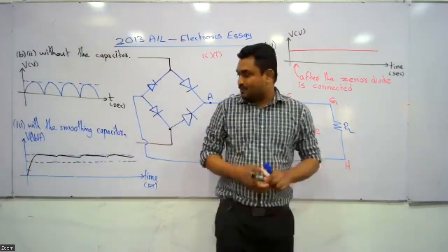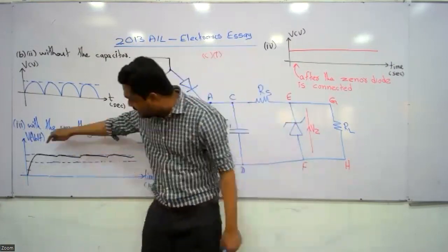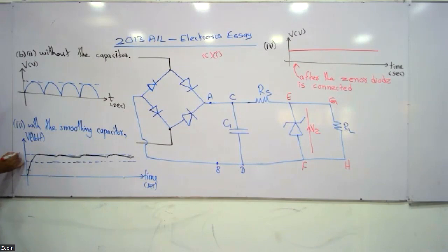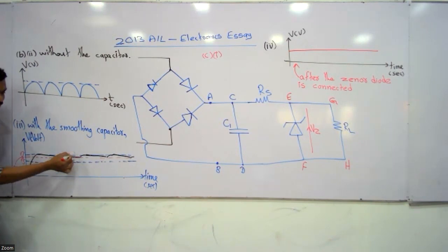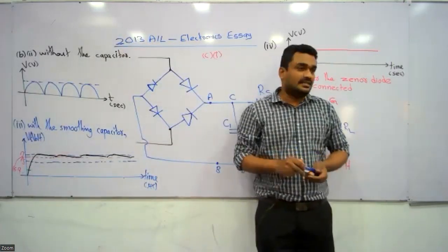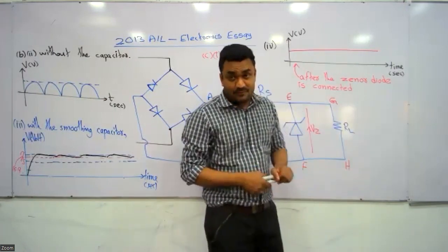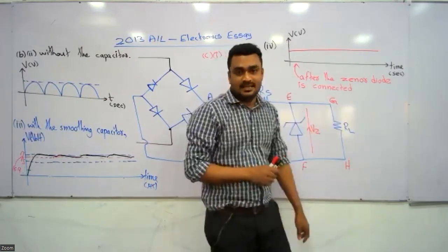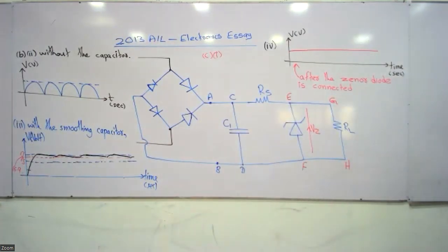So it means the variation of the output voltage here. What was the earlier variation? Let's say this is 17, this is 15. Output voltage reduced between 17 and 15. Now the output voltage is reduced between 16.9 and 17. Maximum 17, minimum 16.9. So the variation of the output voltage is reduced when we use a capacitor with a larger capacitance. Capacitance is measured in farad. You will learn about capacitors in the electric field lesson. Right. Write C Roman number 1.